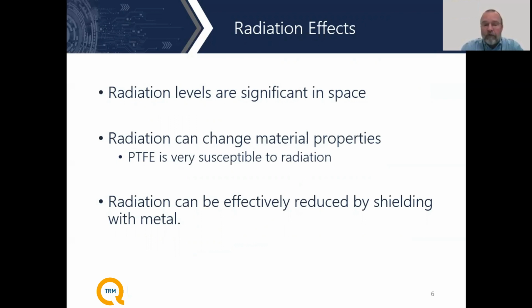And there are certain materials, Teflon, which is a very common material for our products, that are very susceptible to radiation. Basically, what happens is that if Teflon gets exposed to radiation, it very quickly turns into a white powder, and then it no longer behaves like Teflon. So if you're using it as a standoff or any kind of a dielectric, those dielectrics very quickly break down in a high radiation environment. Now, that can be mitigated